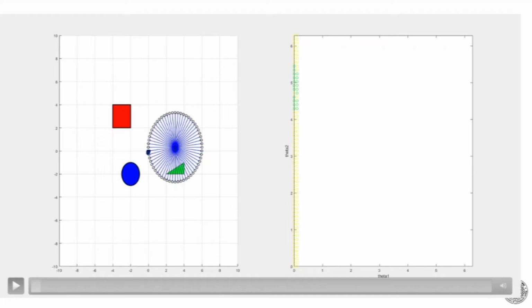So what we have got is a circle now. Now wherever it is hitting, for theta equal to, I think it is a little bit more, over 5 degrees, it starts from 0, 1, 2, 3, 4 like that. It is hitting here, so we color it green. This is how the program works, and this is how we go from Cartesian space, this is my Cartesian space, to C space, this is my C space.